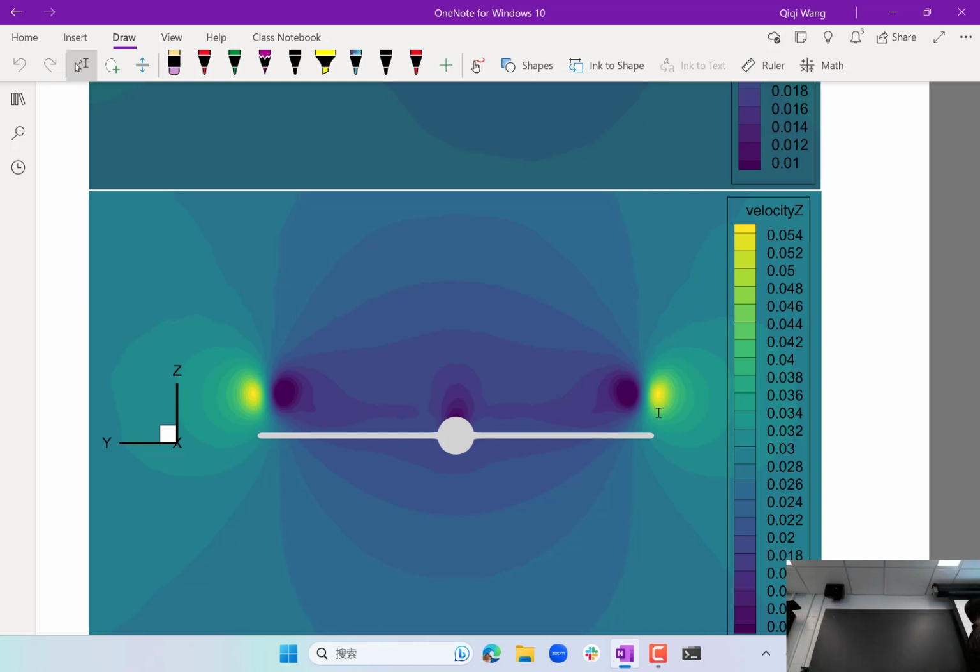But in the coordinate system over here, x is aligned with the airplane itself, which means if the airplane has a finite angle of attack, the free stream is going not exactly in the x direction, but primarily in the x direction with a slight z component, right? So this is why, if you look at the far field, the z velocity is not going to be zero. Zero would be very blue over here, right?